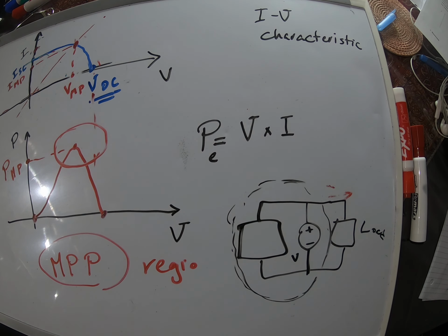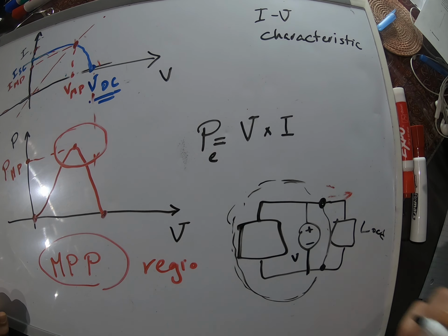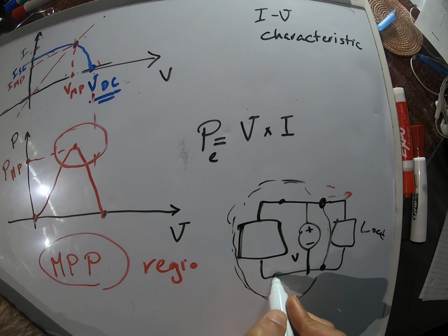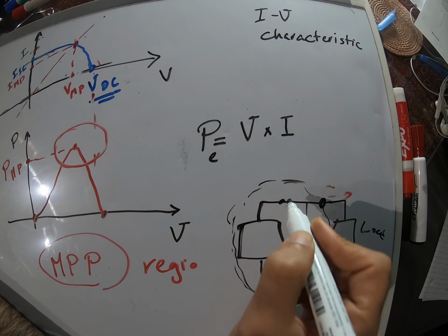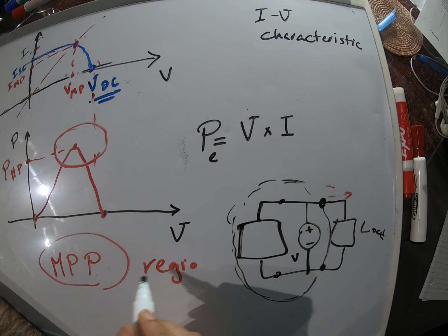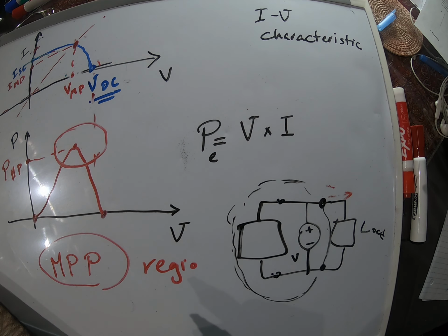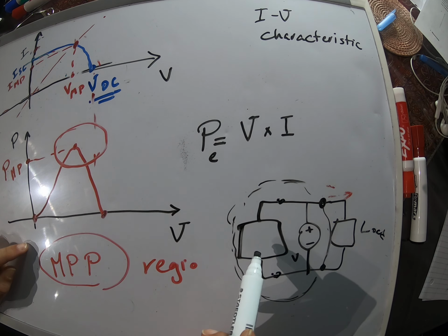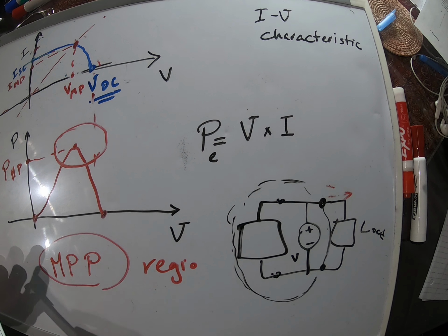To change the voltage that comes out of our solar cell equipment so that we operate at the voltage here, at the maximum power point. So we don't want to change the load voltage that much, but we can change the voltage of the solar cell so that we are operating at this point.